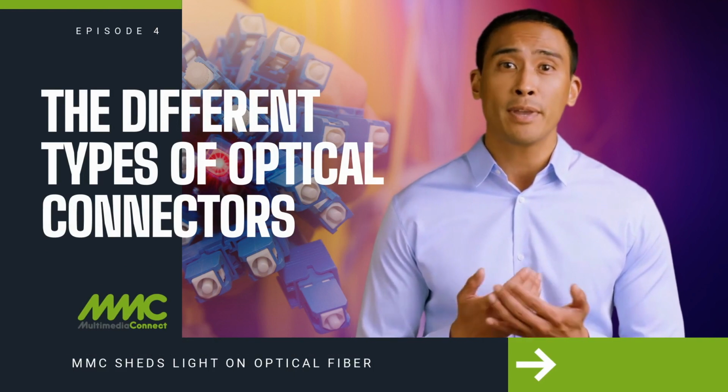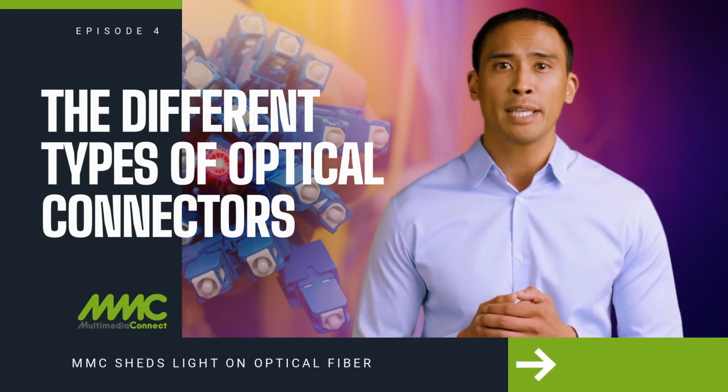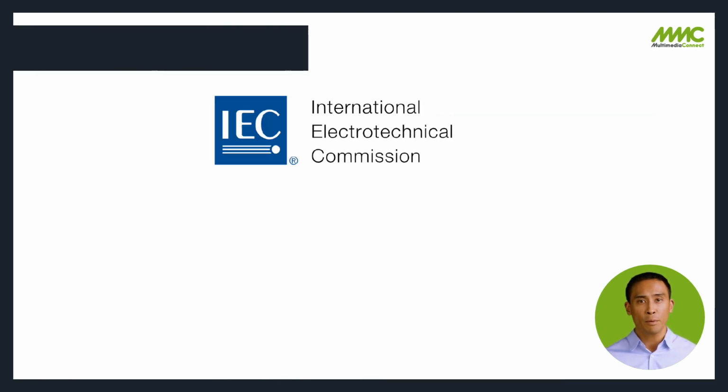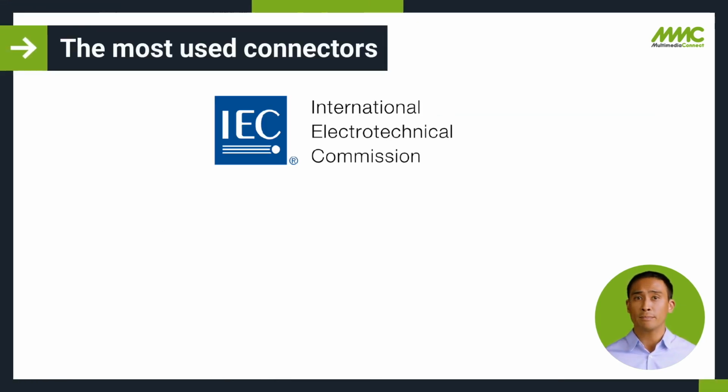Today, I will speak about optical connectivity and the different connectors. We can buy today a number of fiber connectors: SC, LC, MTP, etc. Some are dedicated to specific applications and others are more common. I will focus on the two most used connectors on the market, the SC connector and the LC connector. Both comply to IEC standards.